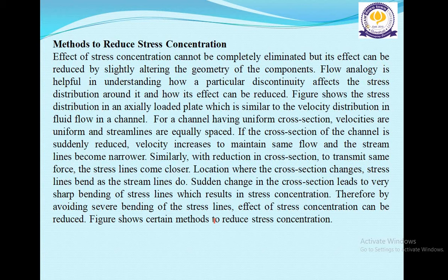Sudden change in the cross section leads to very sharp bending of stress lines, which results in stress concentration. Therefore, by avoiding severe bending of the stress lines, the effect of stress concentration can be reduced. In the next slide we will see a figure that shows certain methods to reduce stress concentration.